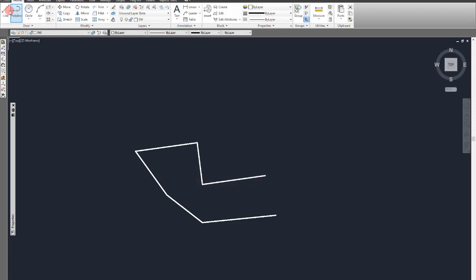Like if I start drawing a line, and if I want to build a perpendicular from this point to this line, I just go to here and you see the green rectangle, which actually shows perpendicular. It's actually not a rectangle, it just shows a 90-degree angle. And if I left click, even if the mouse is not on the point exactly, but if the point is visible, it will make it perpendicular, like here. This angle is perpendicular.